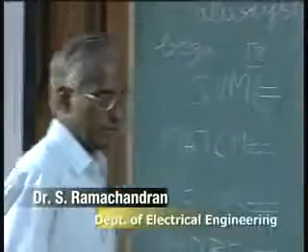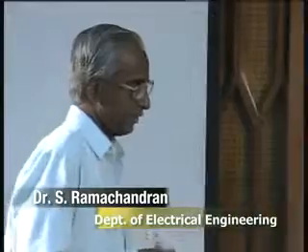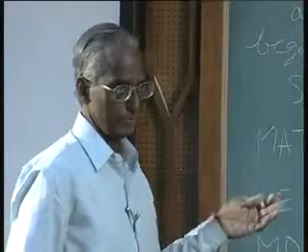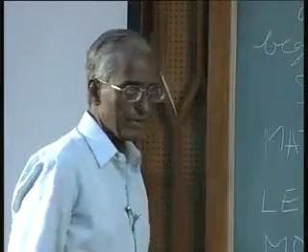That's all the difference. And to summarize the whole thing, we have covered simple gates, the symbol for which is ampersand, and OR, that is a vertical stroke, and for exclusive OR caret, and so on. And then we have seen how to use assign and always blocks in order to achieve any combinational circuits. In this way, you can make any complicated combinational circuits. In the next class, we will be seeing how to model sequential circuits.